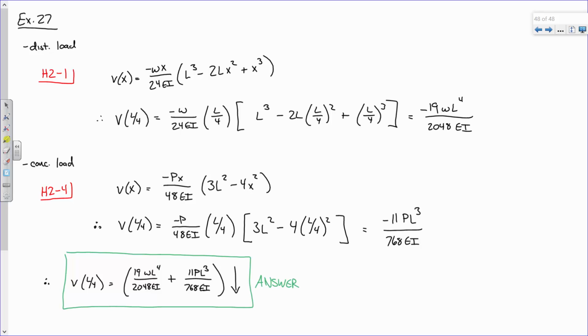instead of just having torsion or just axial load or just bending, what if we have all this stuff? What if we have a section where we're bending it, twisting it, and pulling it? Then we've got normal stresses and shear stresses and all sorts of different scenarios. I propose to you that in those scenarios, you're going to get different stresses depending on the way that you cut. You'll get some stresses this way, some different stresses this way, and some different stresses this way.